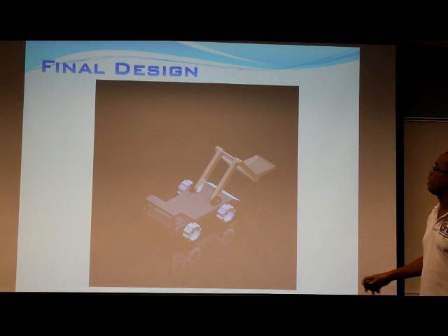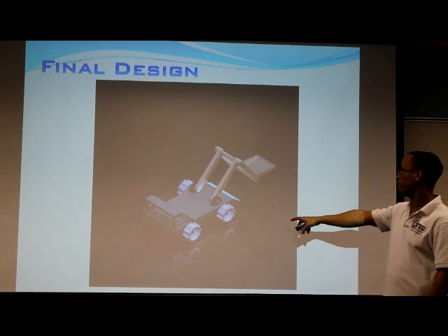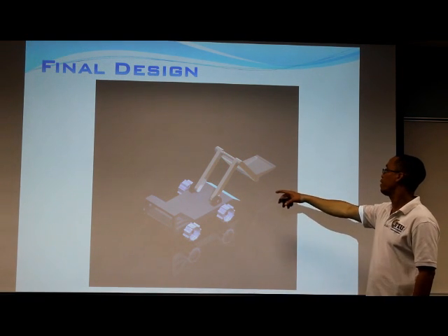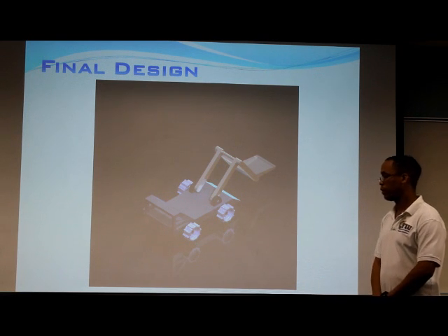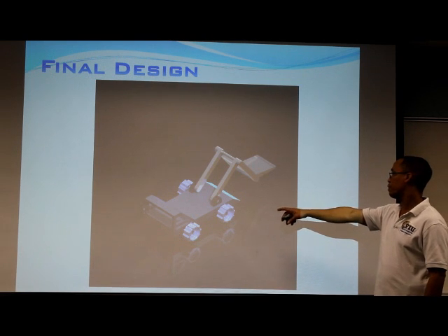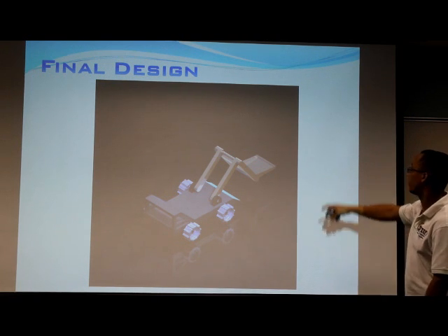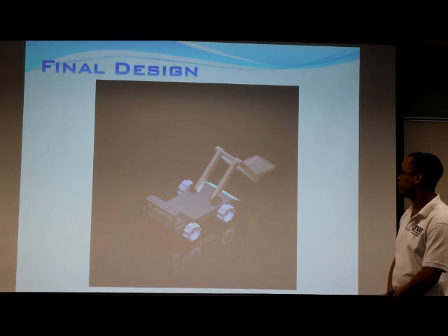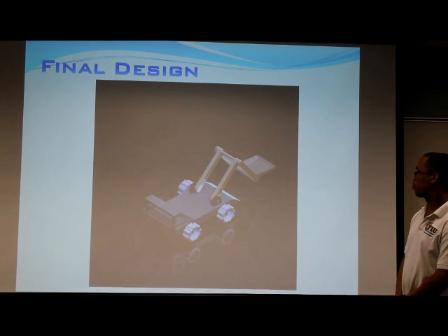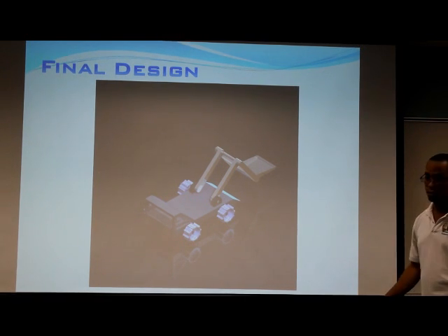This is our final design. Basically, this is the assembly of all the parts that we made in SolidWorks: the tire, the frame, the body, the link, and the bucket. For the material, we selected 2 types. We selected aluminum 1060 for the frame and the body, and for the link and bucket, we selected steel. This picture also shows the final polish of our final design. Now Jose is going to explain more about our project.